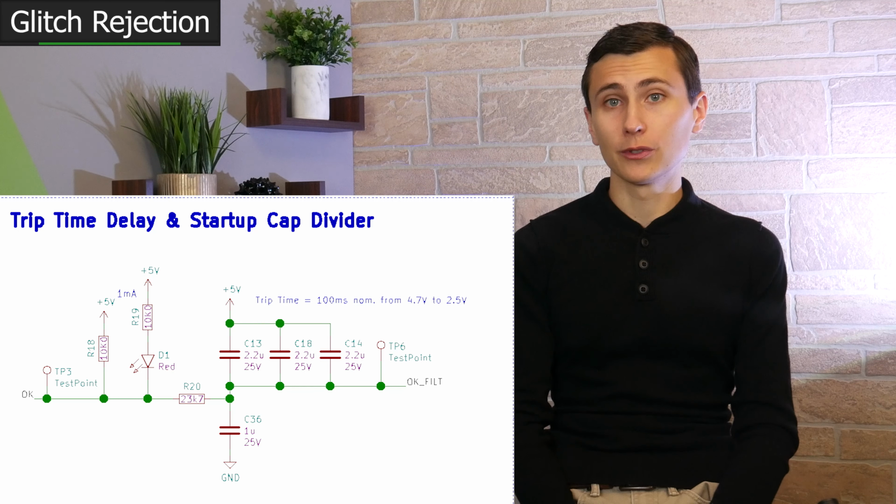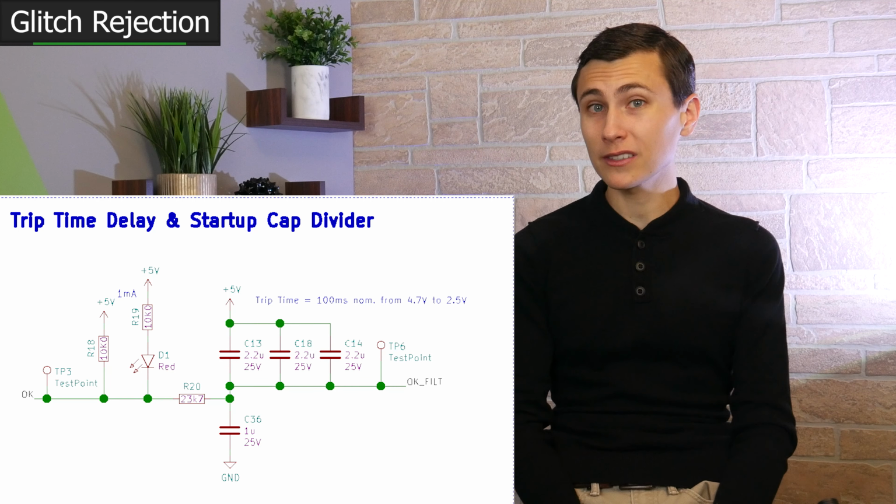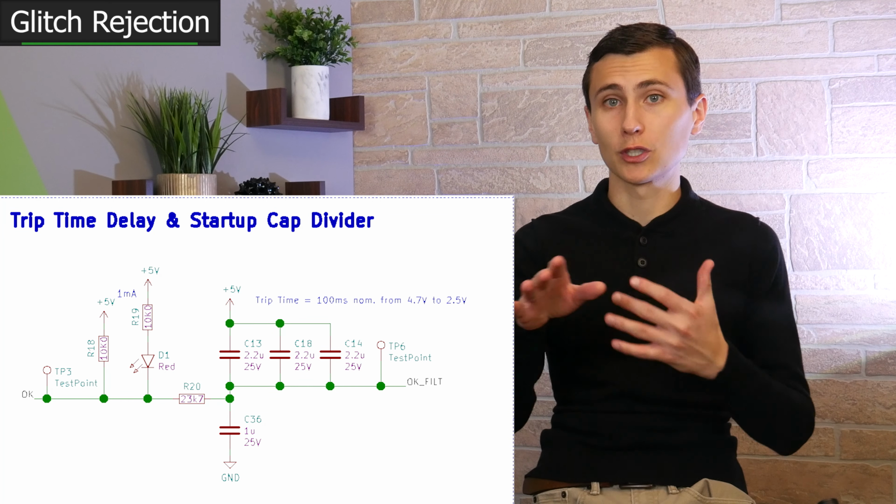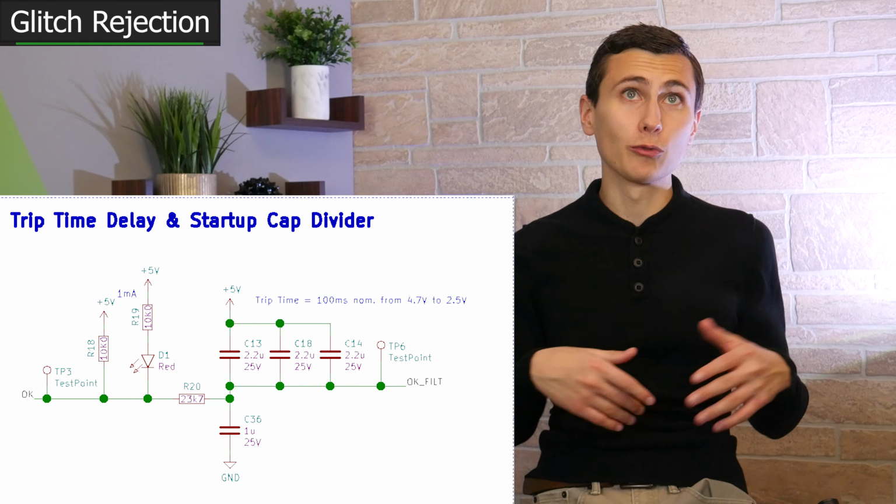It's also important that we use an isolated DC power supply to power this, which will minimize the leakage current from the body of the printer leaking back through the temperature monitor. I mean, not that I don't trust that my printer is appropriately isolated, but we better make sure this is.